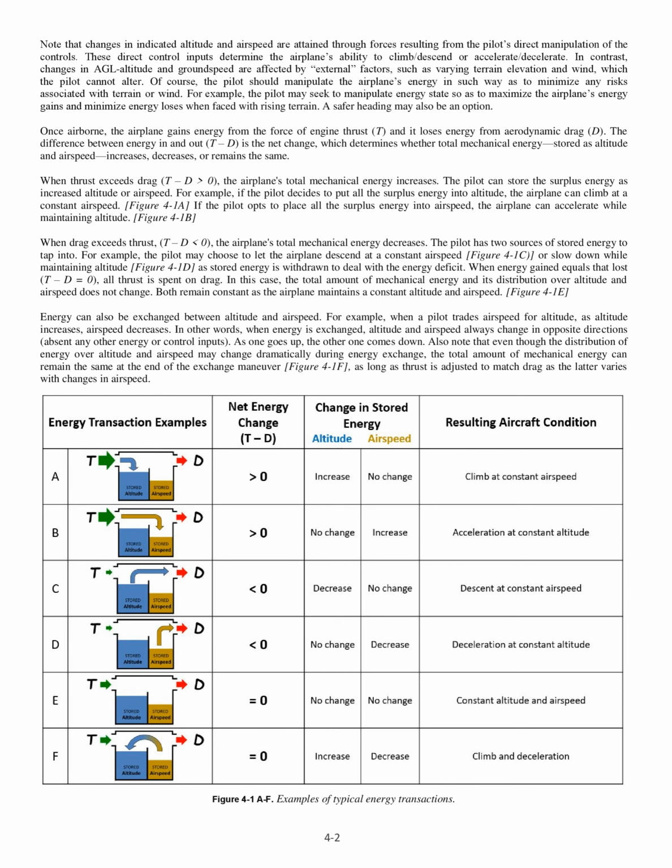Also note that even though the distribution of energy over altitude and airspeed may change dramatically during energy exchange, the total amount of mechanical energy can remain the same at the end of the exchange maneuver, as long as thrust is adjusted to match drag as the latter varies with changes in airspeed.